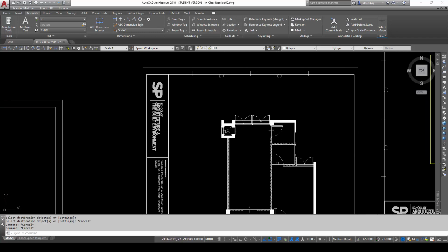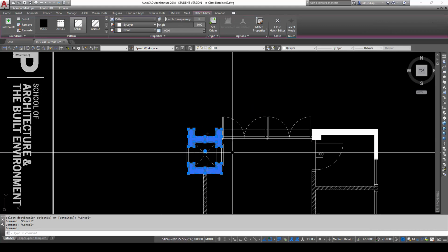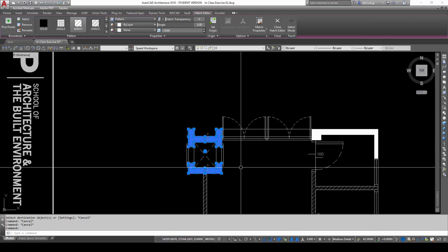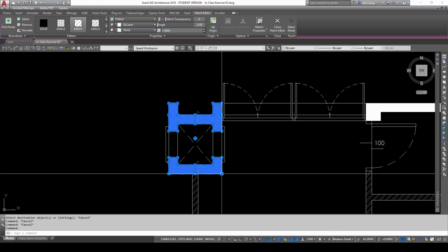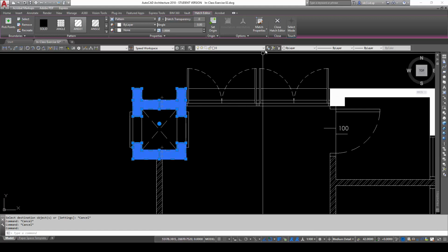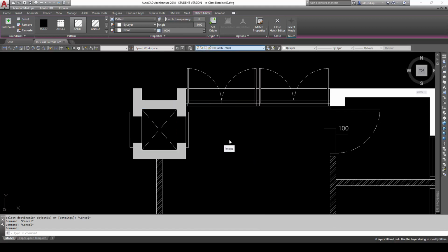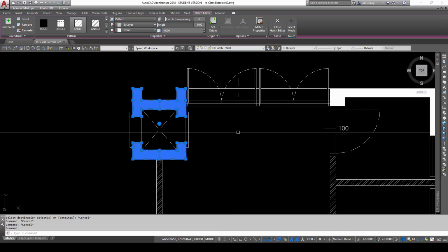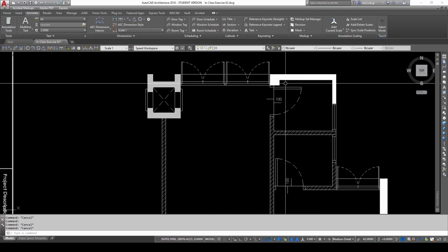And these solid hatches here are belonging to the superstructure, okay? But we do not know what all these structures are like. So that's why in our interior design practice, we are not going to touch them too much. We will leave them shaded black, okay? So shaded black, we will simply change them to hatch wall layer here. Okay, so let me try to see if we can select more of these as well.